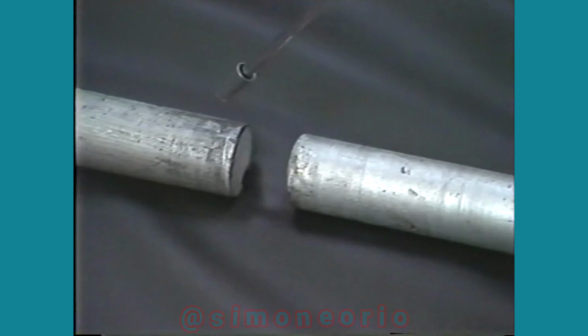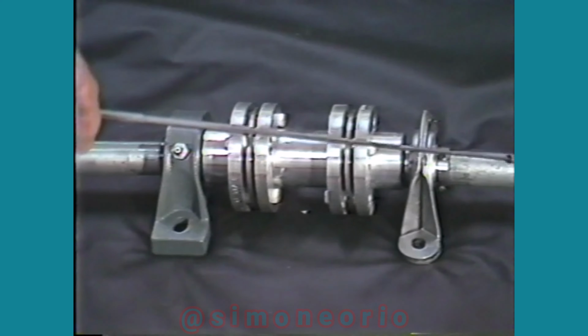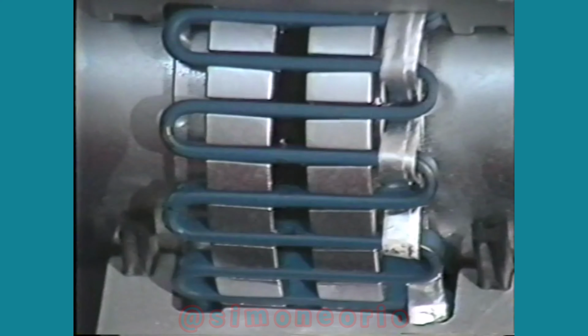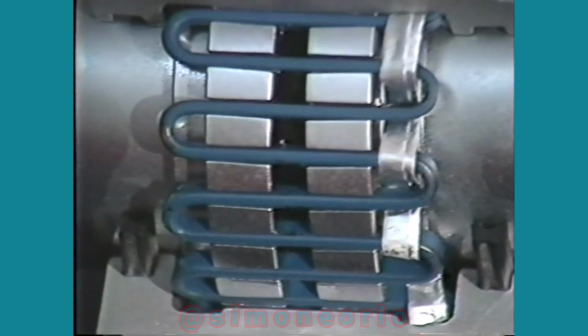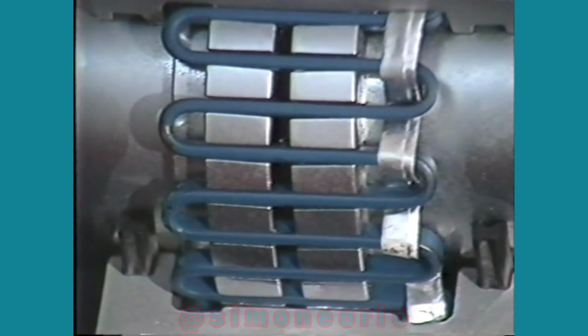This shaft may move over and push on that shaft. If the pressure is carried through the coupling, this action will put extra load on the bearings supporting the connecting shaft. The bearings in the original shaft were probably designed to take this load. When the load is transferred to the other shaft, those bearings may fail if they've not been designed to accommodate thrust loads. Other damage may occur as a result of end float. A coupling that can change in length while running can prevent this load transfer.